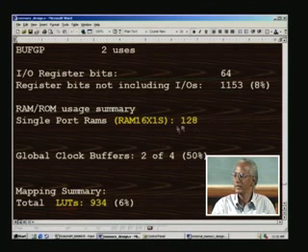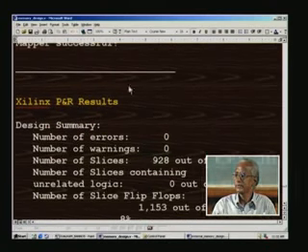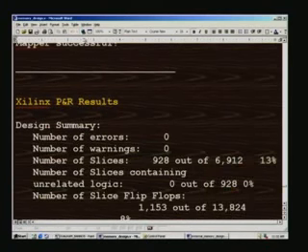We didn't specifically mention this, but automatically the tool has done it. In terms of LUTs, it takes 934 LUTs, and it's only 6% of the 600,000 gates. And this RAM is over and above those LUTs.